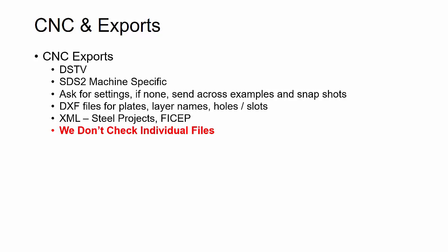Now, sometimes if there are too many different file formats and different standards and exports that we need to do, I'll actually try to work with the fabricator and say, can we deliver the SDS2 or the Tekla model to you and then allow you to extract the exact files and things that you need specific to your processes and to your shop?